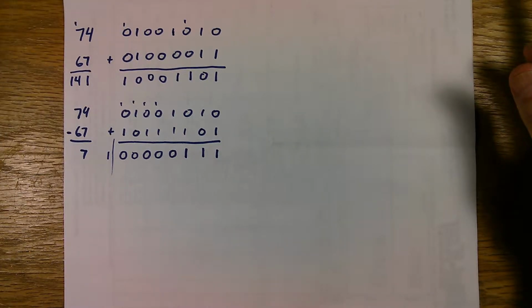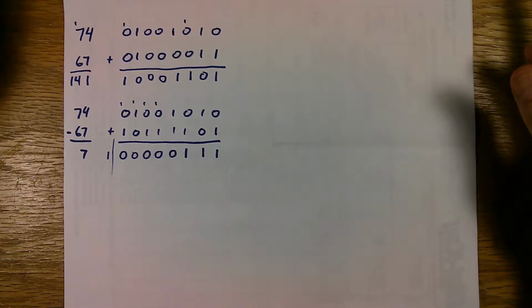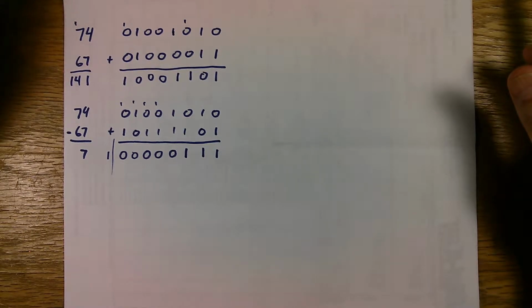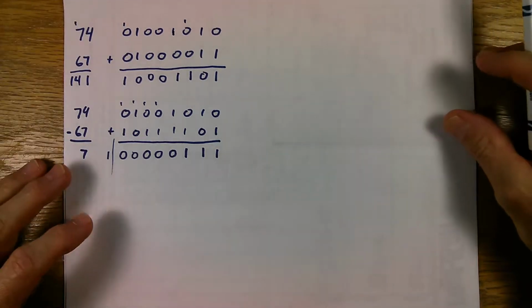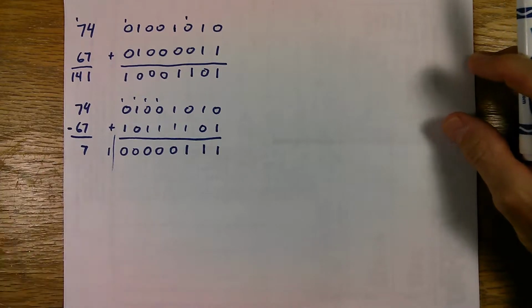There's 256 different combinations, just like I described earlier. If it's a signed char, just a char, it can take on a range of numbers of minus 128 to plus 127. And if you work that out, you'll see that there's still 256 different combinations, from minus 128 through 0 to plus 127. And like I said, you've got to be careful when you're playing with these numbers. If you don't declare them as unsigned and you're expecting them to be unsigned, you might have some weird results.